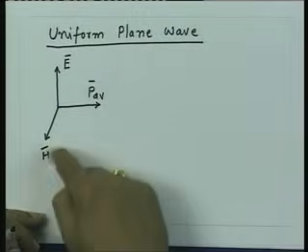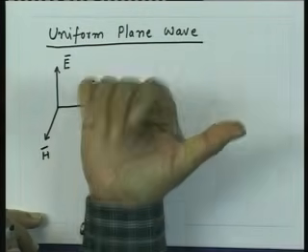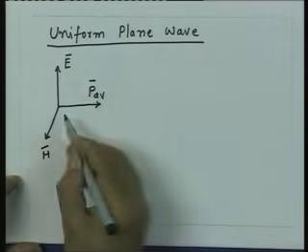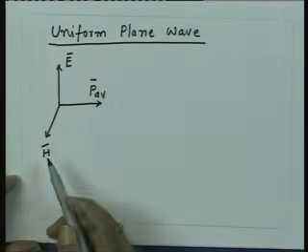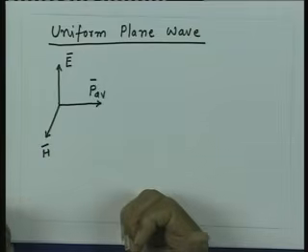So, since we are taking the cross product of E and H, again we point the fingers in the direction from E to H, and the thumb should give me the direction of the cross product. This direction is same as the direction of the wave propagation also, because we have seen when we talked about uniform plane wave that E, H and the direction of wave propagation essentially form the 3 coordinate axes in the same sequence. That means, if my fingers point from E to H, the thumb should go to the direction of the wave propagation. So, we correctly get the direction of the average Poynting vector, which is same as the direction of the wave propagation. That is one.